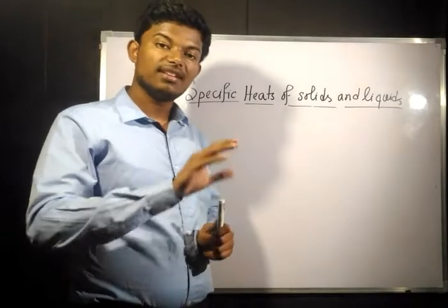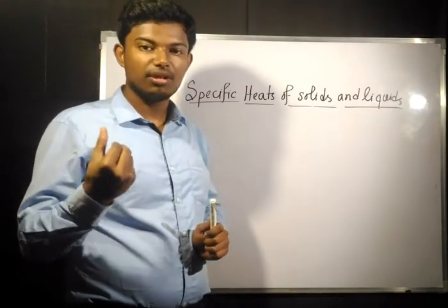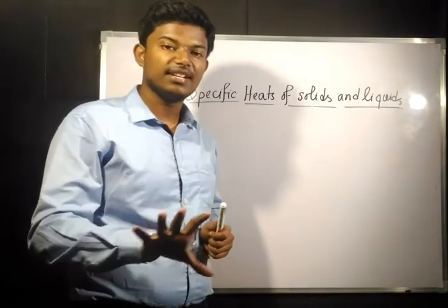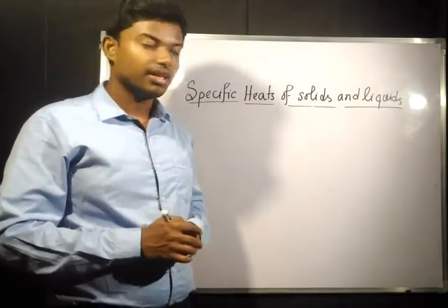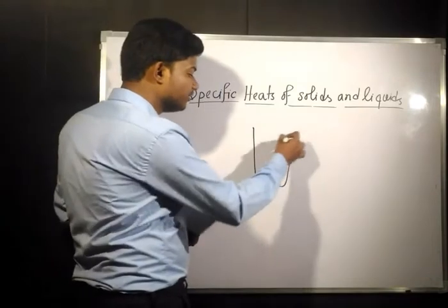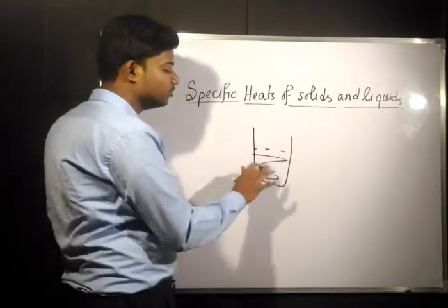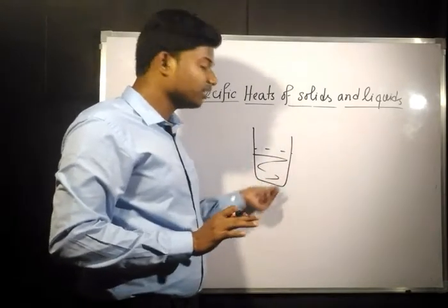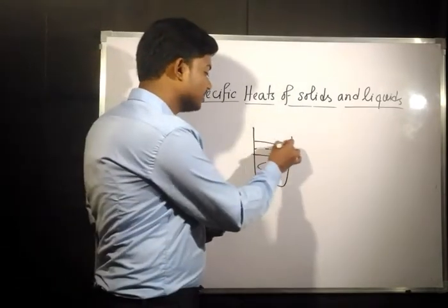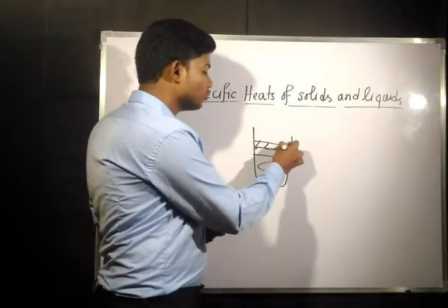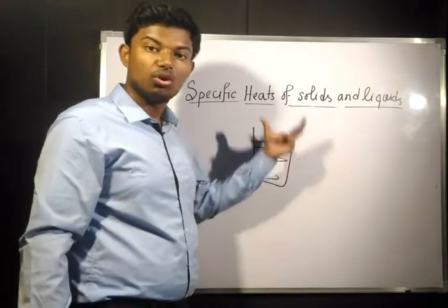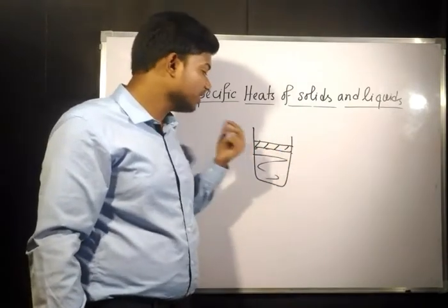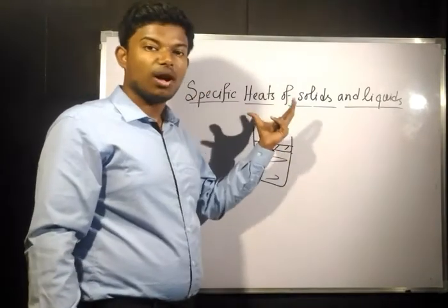It is going to be considered as the same case, because whatever work you are going to get in the case of constant pressure is very negligible. We can neglect that. Now for a liquid, if you take some constant volume, even if you don't put the stoppers when you are giving heat to a piston, it will not go up, or even if it goes up, it's very negligible. You can say that it doesn't go up.